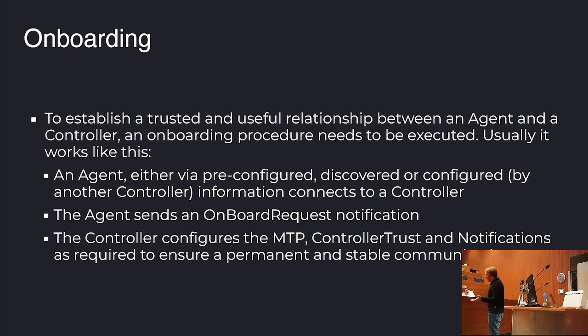And if you don't do that, which is an important part of the onboarding, then the device will never talk to you again. So you might have a connection to the device, but you don't know that the device is there because you have no idea when it was last rebooted. Which is especially important if you're using something like MQTT, where you don't have a direct connection between the two parties. But it is very important that you set up the notifications in order to keep communicating with the device.